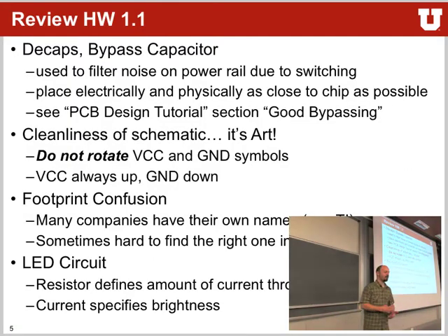All right, a quick review for homework 1.1, a couple of pointers I want to give you while you make your schematics. You might hear words like decaps or bypass capacitors. These are capacitors that you put onto the power rails of your microcontrollers. Basically, they help smooth out fluctuations on your power lines for your microcontroller. And once you lay them out, after putting them in the schematics, it doesn't really matter where they are in the schematic. You try to put them physically close to where you want them placed later on your PCB, because that makes it easier to read a schematic and compare it with your PCB itself.